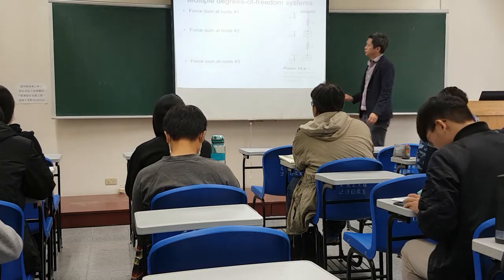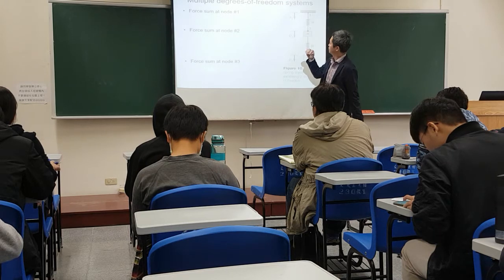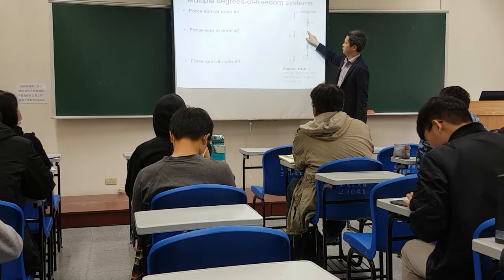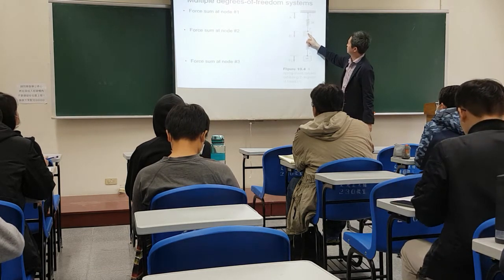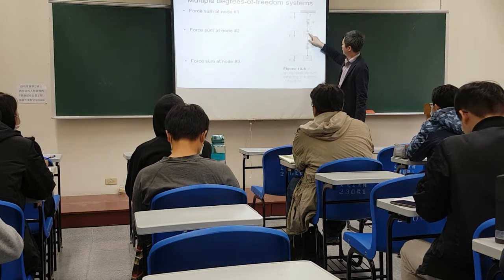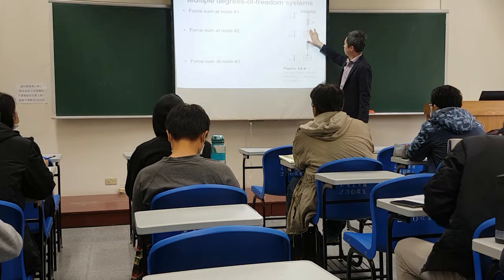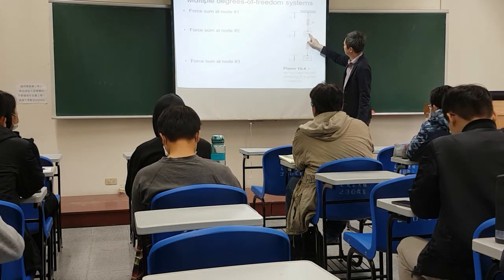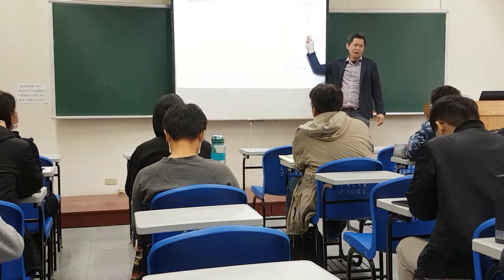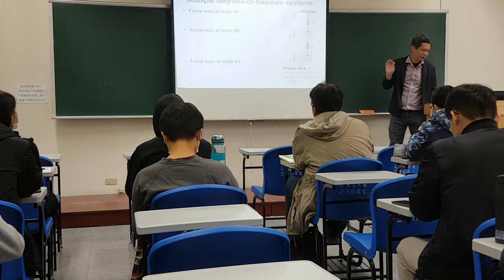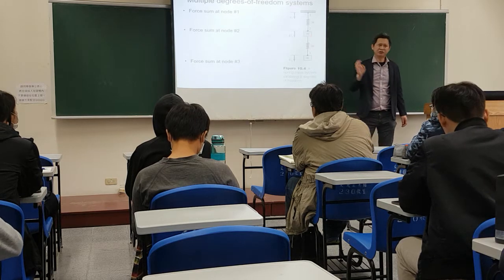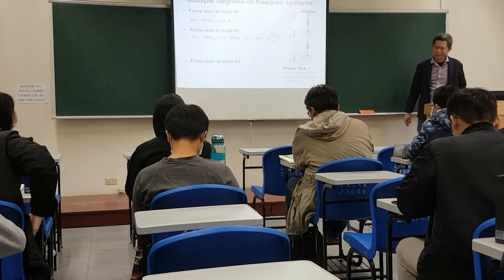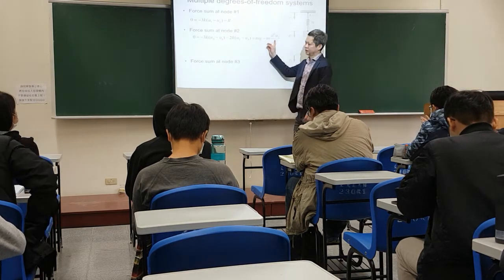So the idea of doing forced vibrations is you have to add inertial force on the node where the mass is located. For example, I now have 2 springs and 2 masses. When this is subjected to harmonic forces or harmonic vibrations, the inertia of the mass is non-zero. So as a result, when you're writing the force summations, you have to convert the acceleration into the inertial force.